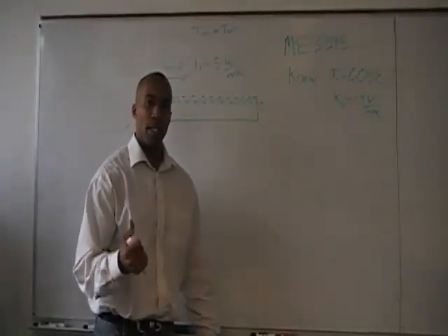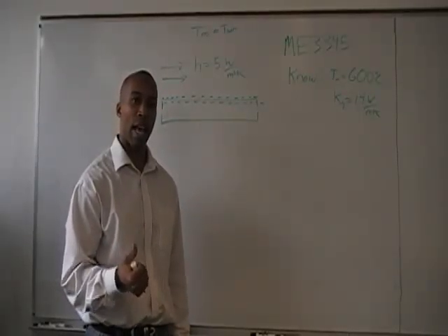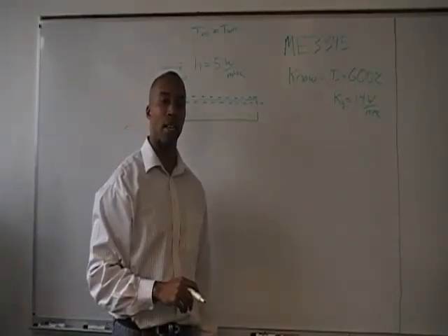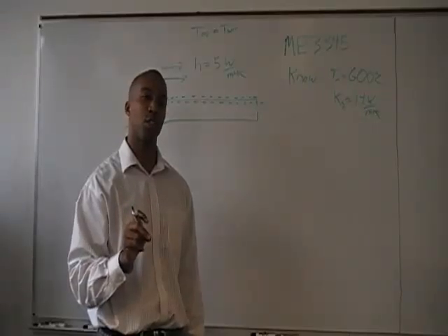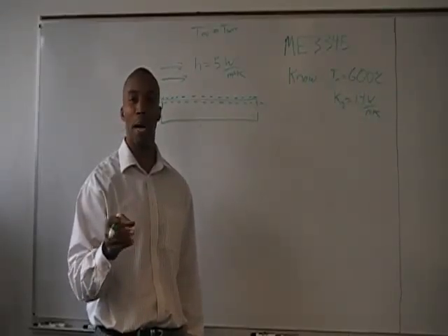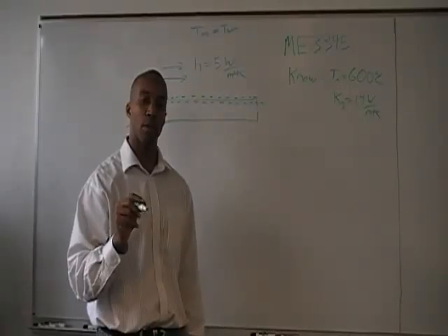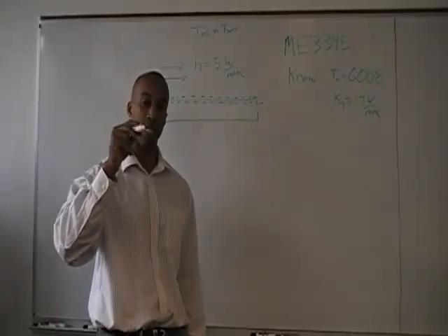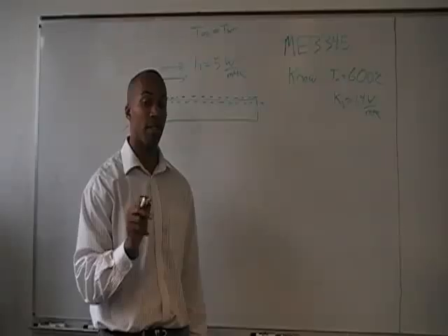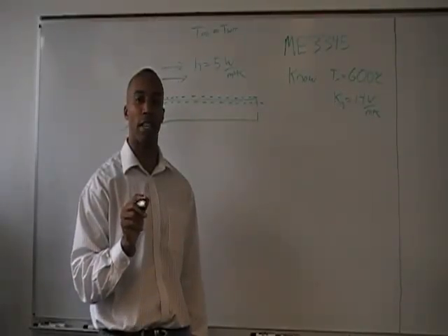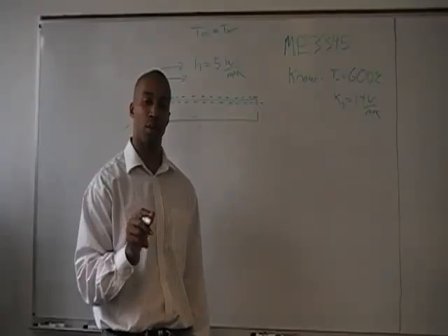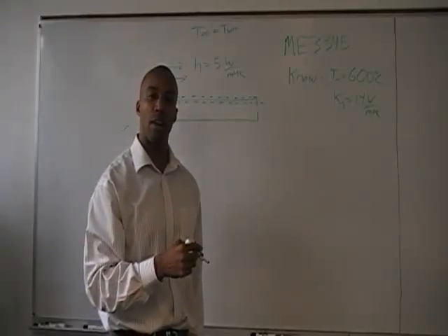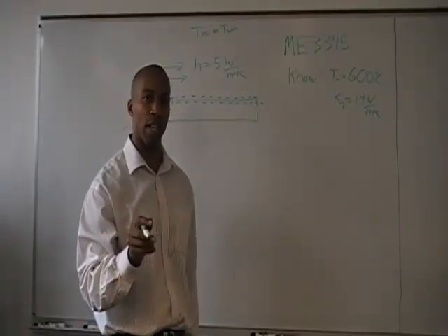Now, as we work through this problem, we see we have radiation, convection, and we're going to have conduction because we're talking about some sort of temperature gradients being in this glass. There's a couple of things that we really want to pay attention to in this problem. As you know by now, with radiation, Stefan-Boltzmann's relation shows that the radiation heat flux is proportional to the difference of the temperatures raised to the fourth power. Because of that, you always have to use the unit Kelvin in calculating radiation. So we're going to have to be careful to make sure that we convert our values of Celsius to Kelvin whenever we're computing the radiation component of this problem. Otherwise, we would get the wrong answer.